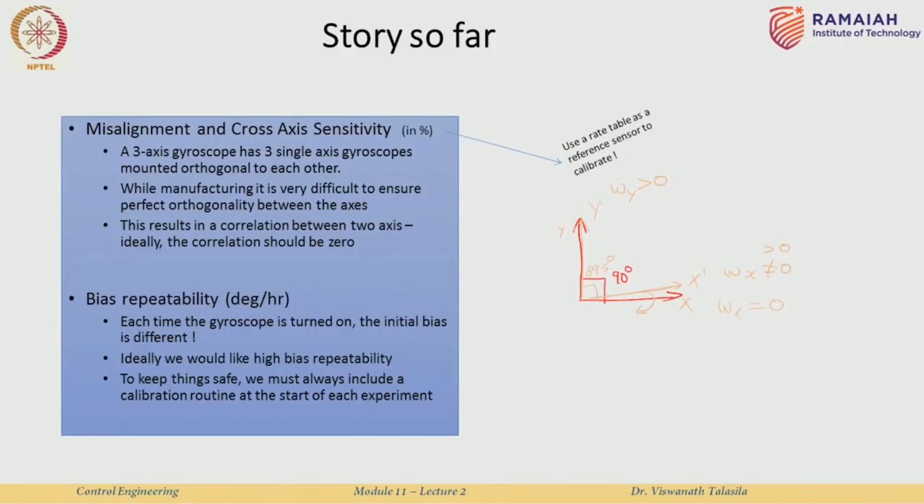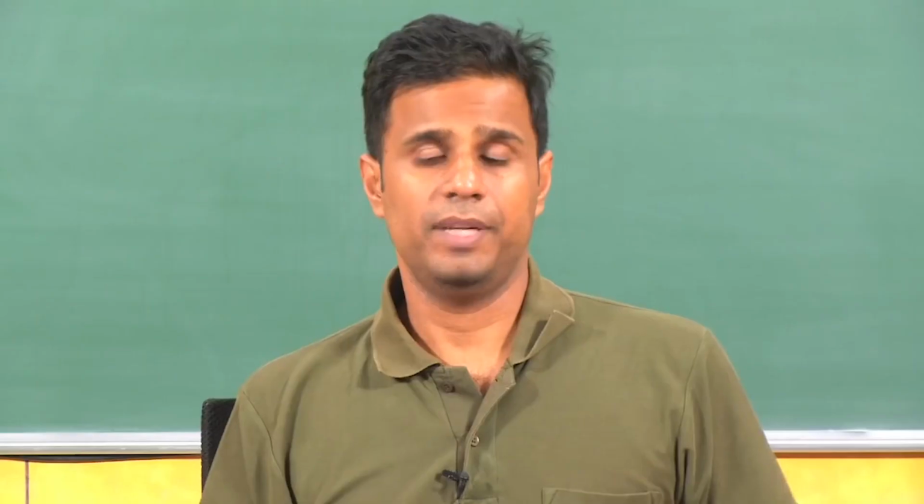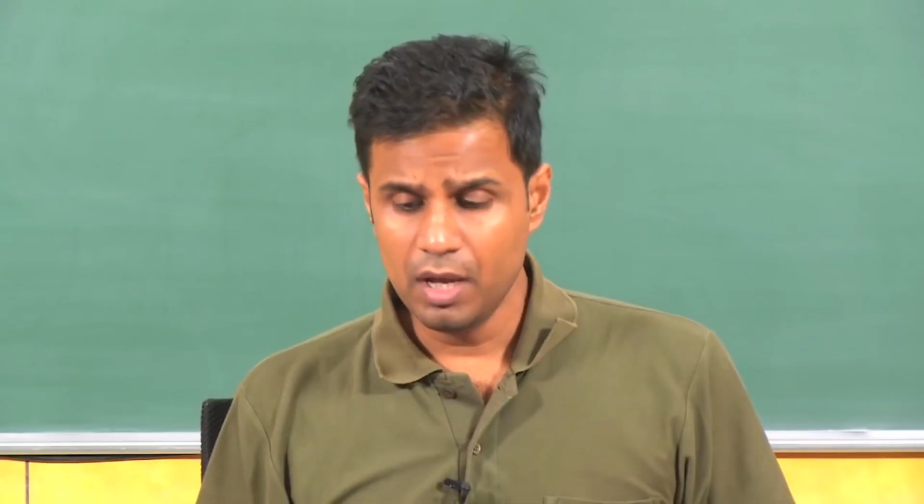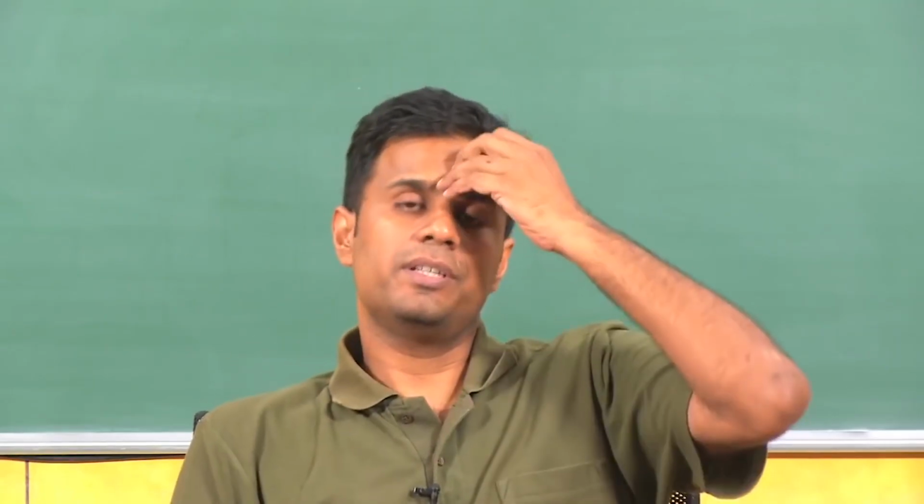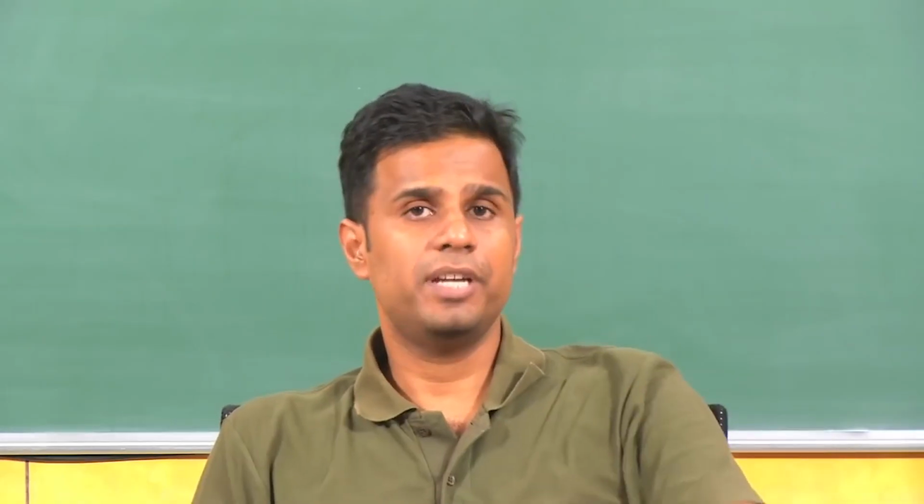So, all these noise terms, they come together and they basically corrupt your measurement. True plus noise, and noise, as you can see, we have seen about 5 different types of noise terms. Each one of them affects the overall computation in a slightly different way. The most dominant one is a bias, that is the largest value, and for most applications it is generally enough to compensate for the bias.